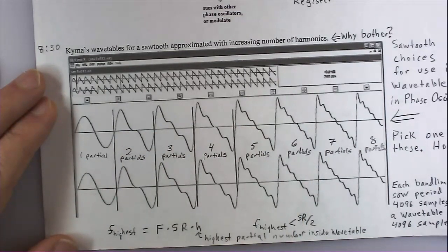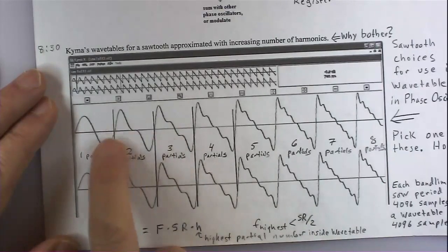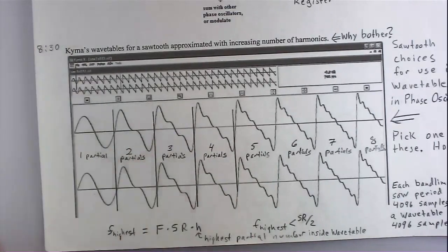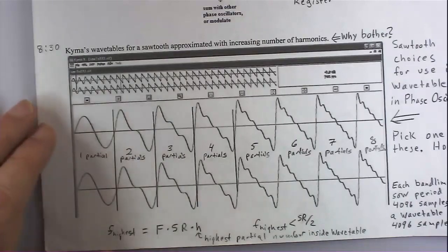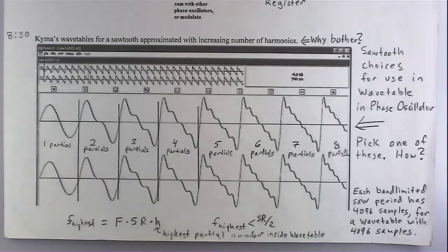And every repeating waveform that you can make is made up of exact integer multiple frequencies. You can't have anything else. If you think about it, say in this one you had one that was 2.5 times the frequency. Well, the thing wouldn't repeat, right? Because instead of going through the upper one twice in one period of the fundamental, it would go through 2.5 times, and then it wouldn't be at the same spot that it started with at the beginning. So somehow convince yourself that's true, because that's a really important factoid: any exactly repeating waveform has only integer number harmonics.